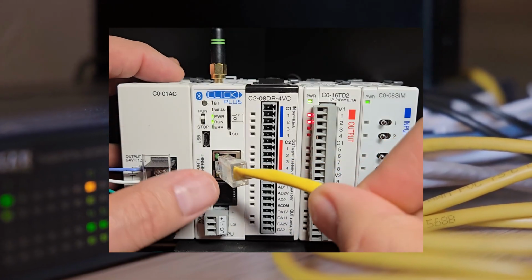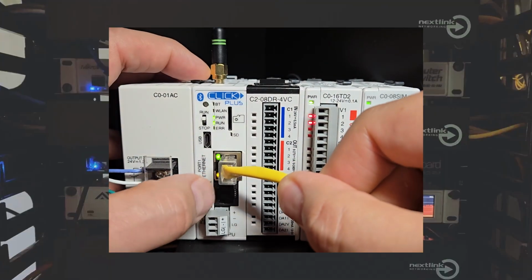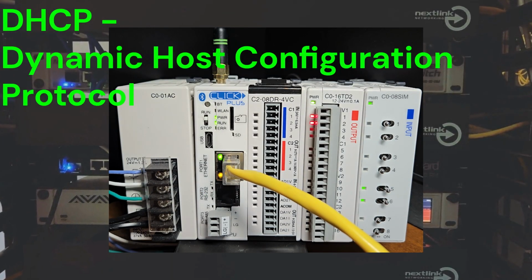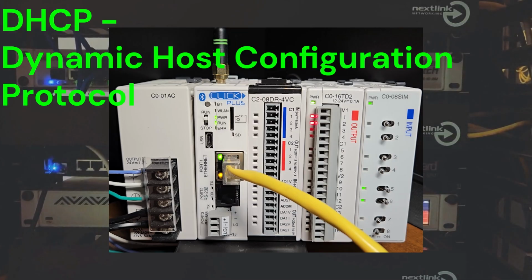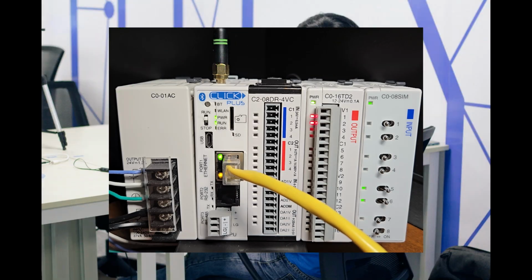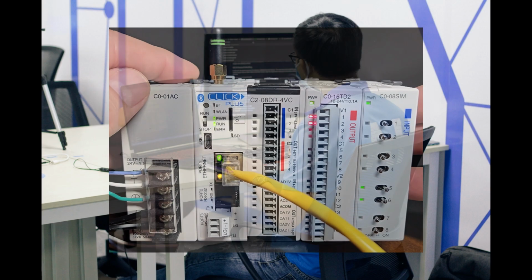Port 1 of the Click PLC defaults to DHCP. Dynamic Host Configuration Protocol automates the assignment of IP addresses and other network configuration parameters to devices on the network. It's the simplest way to establish that initial communication, especially with a factory default device.